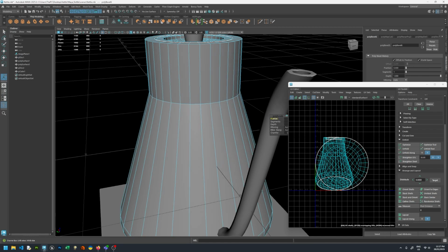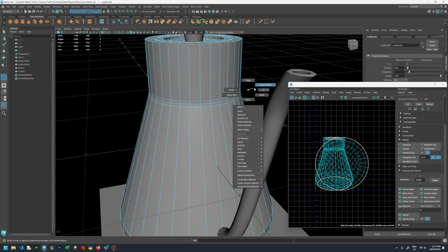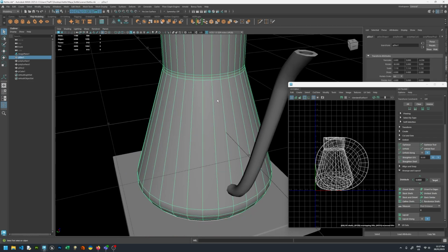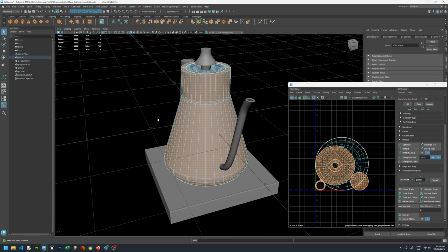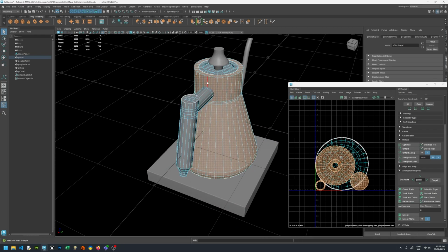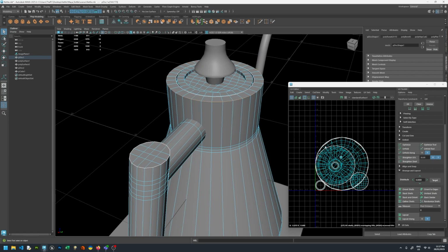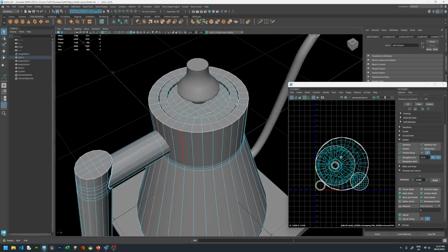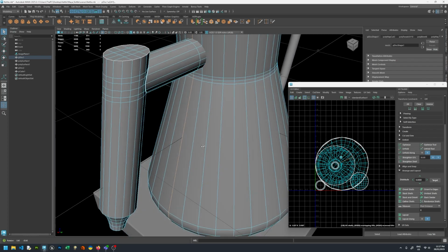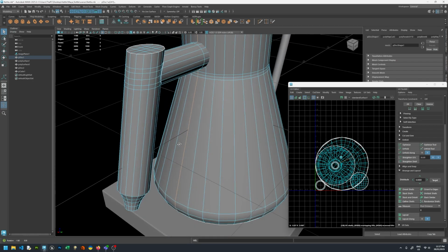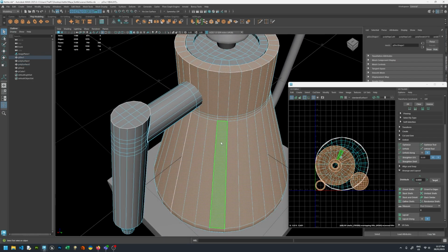Oh, and I actually want to smooth and bevel. So I wanted to bevel this one so it's a bit more obvious. If I make it a soft edge, you won't be able to see it. Let's put some more edges there. All right, so unfold. It's fine, and then I'll cut that 1 edge down the side. I didn't do the top yet. I'll cut this one. Shift X to cut. Unfold that. Have a look. Yep. Again, still looks good now.